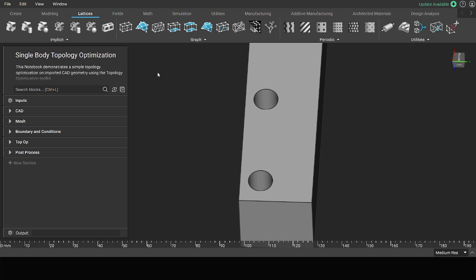And we're not going to make this video about learning topology. We can have another video or some YouTube series on that. But just breezing through what it does, we can create lattices. With additive manufacturing, we have the ability to print hollow structures, and we can reinforce them with lattices. So we can have a very lightweight but strong part. And we have a lot of lattice methods and lightweighting methods.